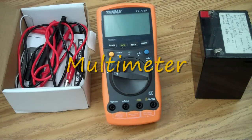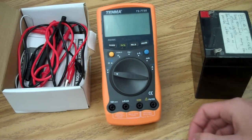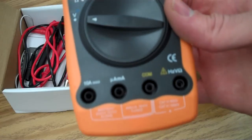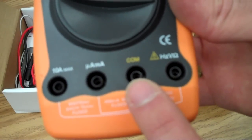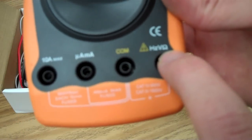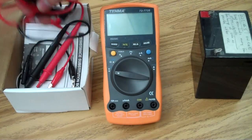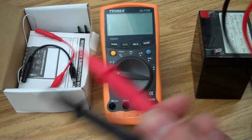Alright, so the first instrument we're going to look at today is the digital multimeter. And as I said previously, the multimeter can measure voltage, resistance, and current. That depends on where you plug in your inputs. If we look here, we see voltage, resistance over here, and these ports over here are for amps. So what we have to do is plug in our test leads, which are these two probes here.